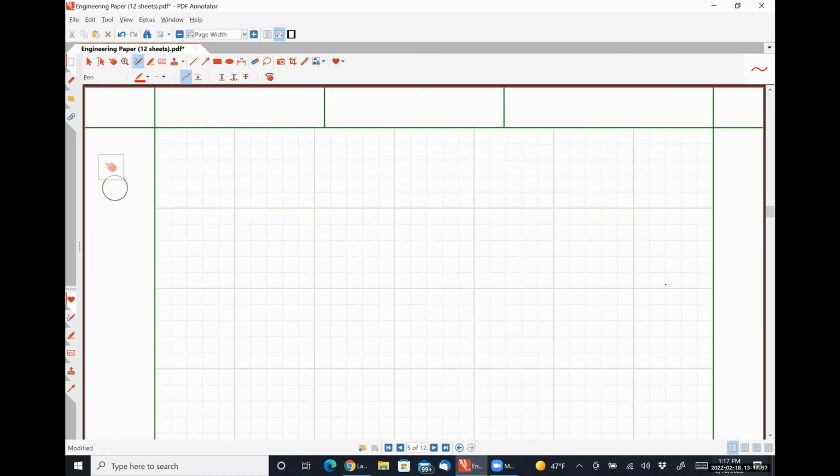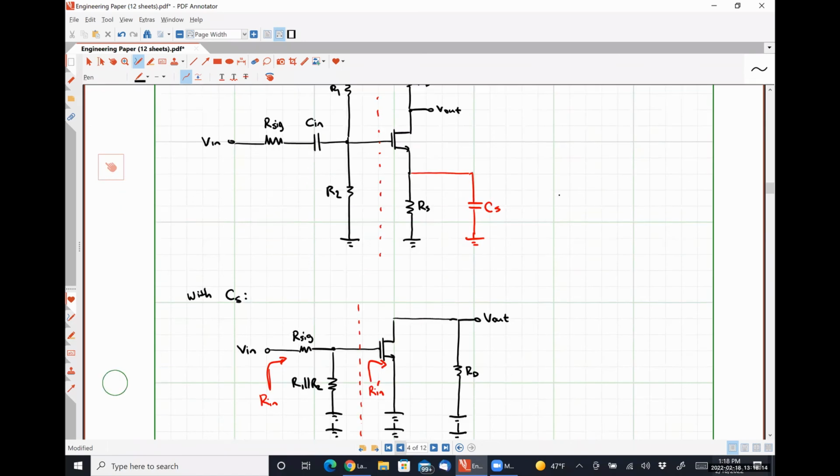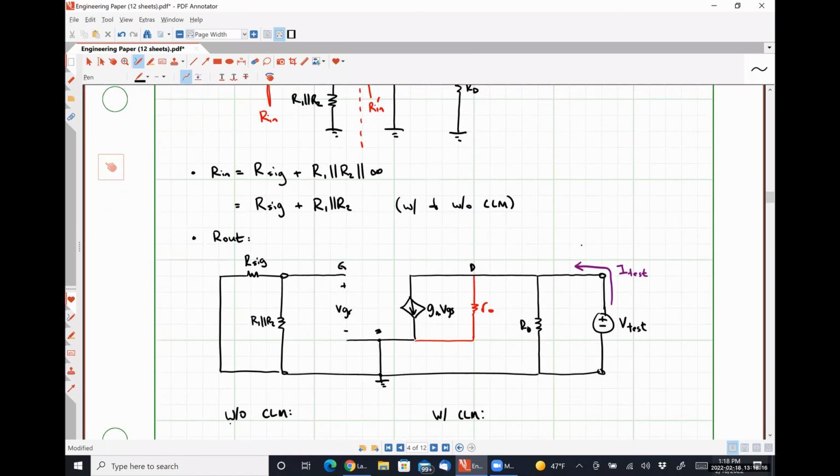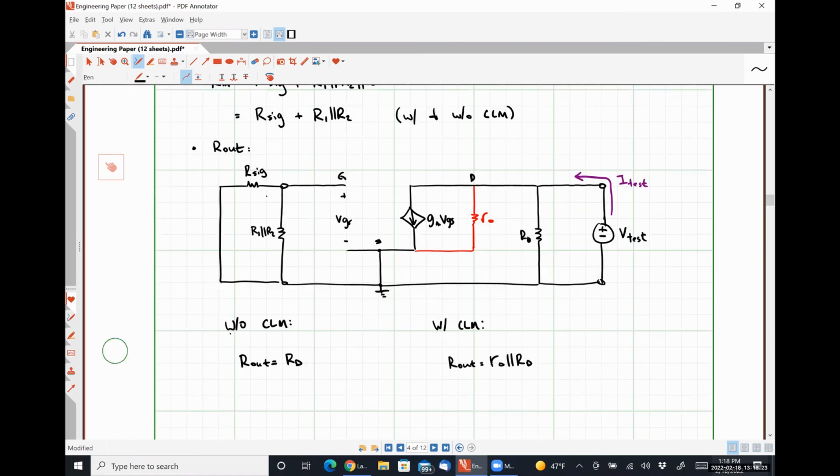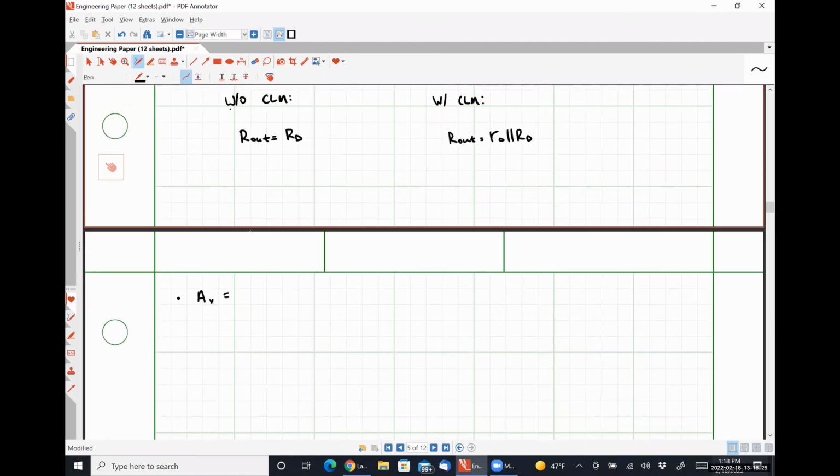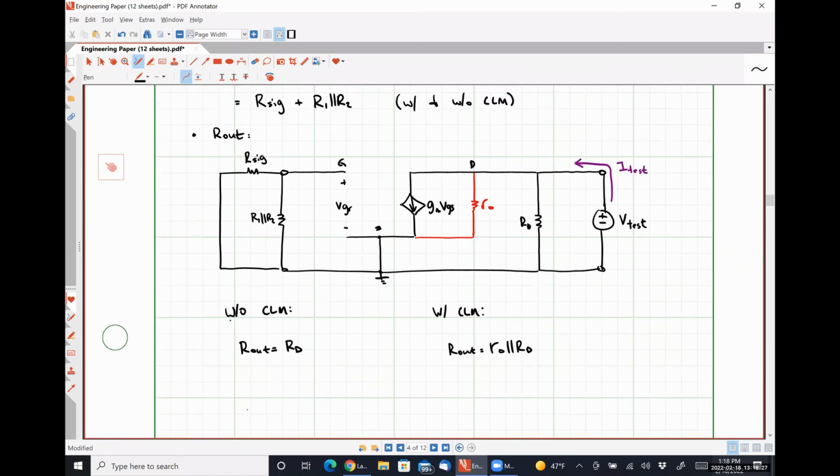All right. Our last quantity to determine then is our voltage gain. Do I need to go back to the last page or? Sure. Whenever we're determining common source things, we're looking at it as AC, so our capacitors are already shorted.